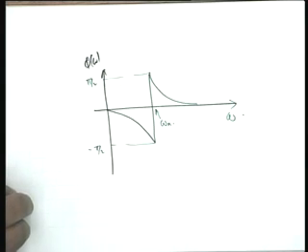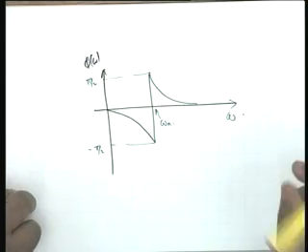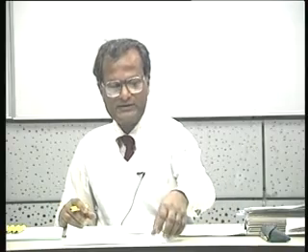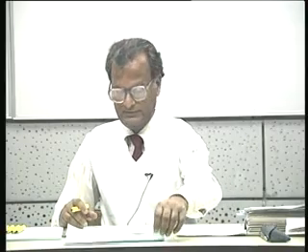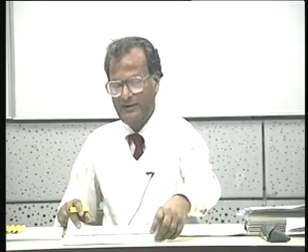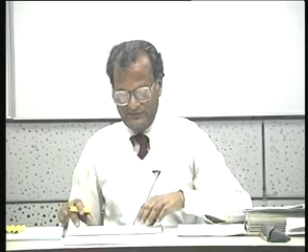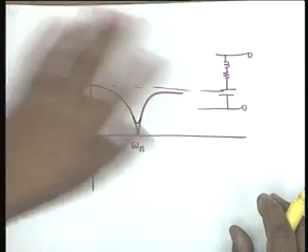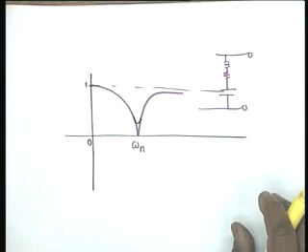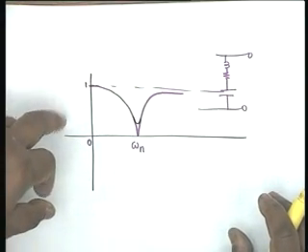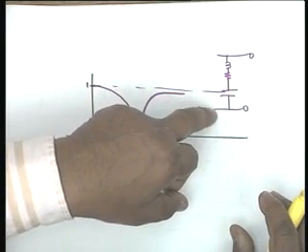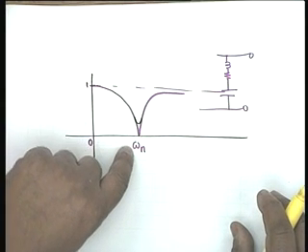Next, the third part, which very few people have attempted, and I thought that would be very simple. This concerns the half power frequencies. Now, obviously, if you look at the magnitude plot, the maximum power is at DC or at infinite frequency, the maximum value of the magnitude function. And half power would therefore mean the frequencies at which the magnitude becomes 1 by root 2. It has nothing to do with omega n.